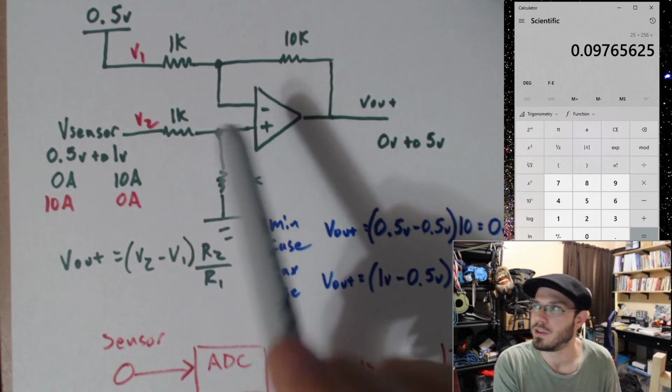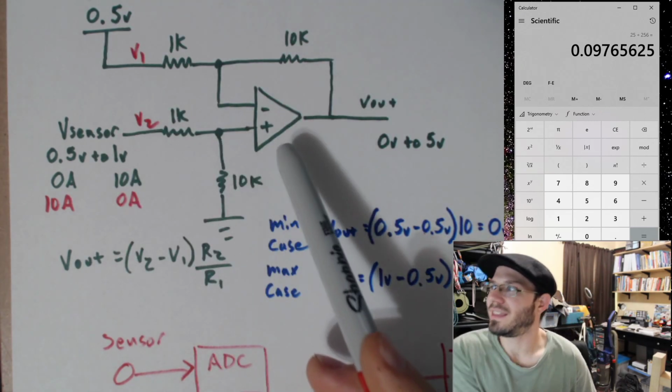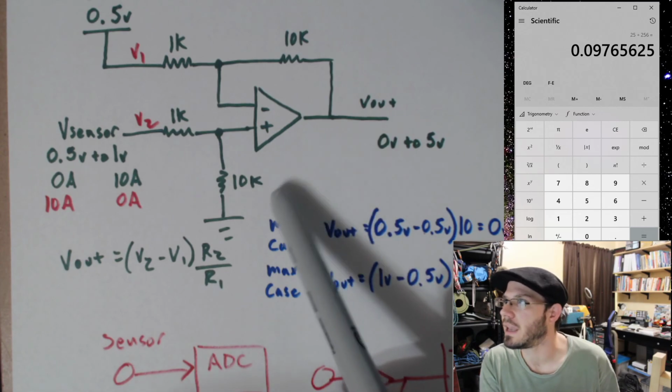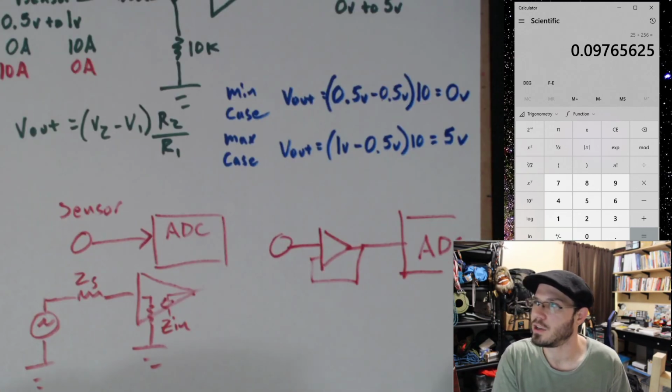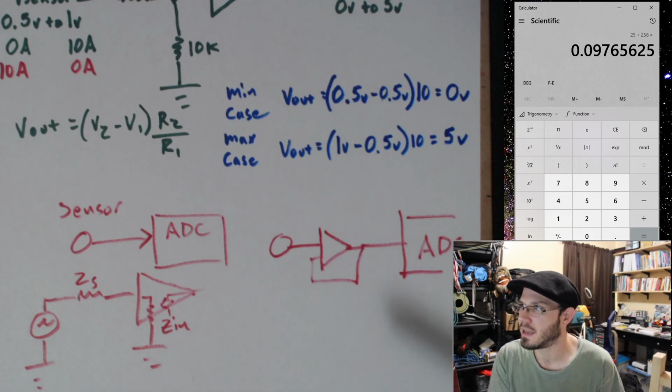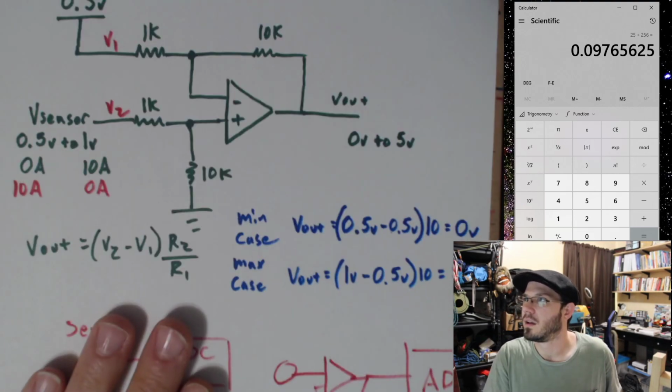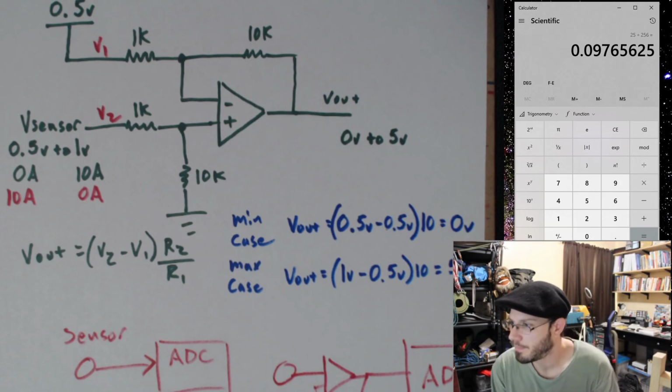So please do yourself a favor, get comfortable with this circuit. This is not a hard thing to implement. We're just talking about 4 resistors and 1 op amp. You should use 1 op amp anyways as a voltage follower. Why not just do it properly?